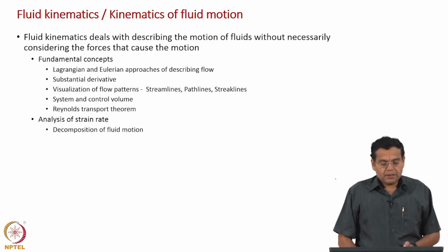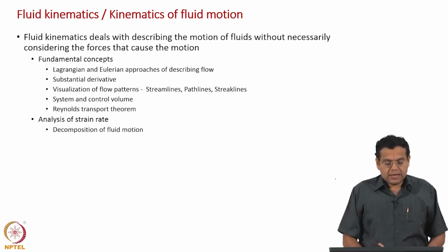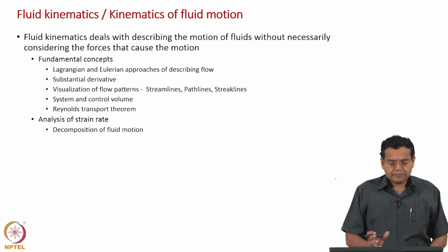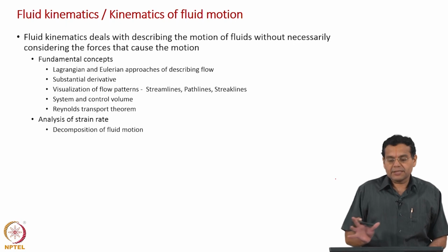What is decomposition of fluid motion? That is expressing the velocity gradient tensor in terms of the strain rate tensor and the rotation rate tensor, which means we are decomposing the fluid motion into deformation and rotation.